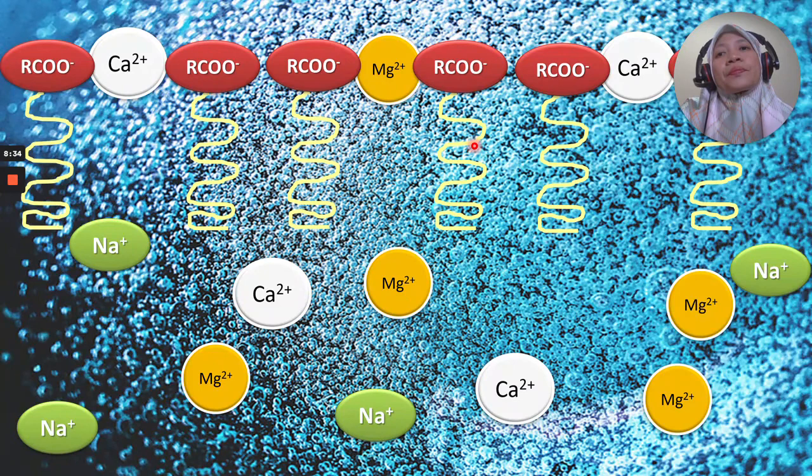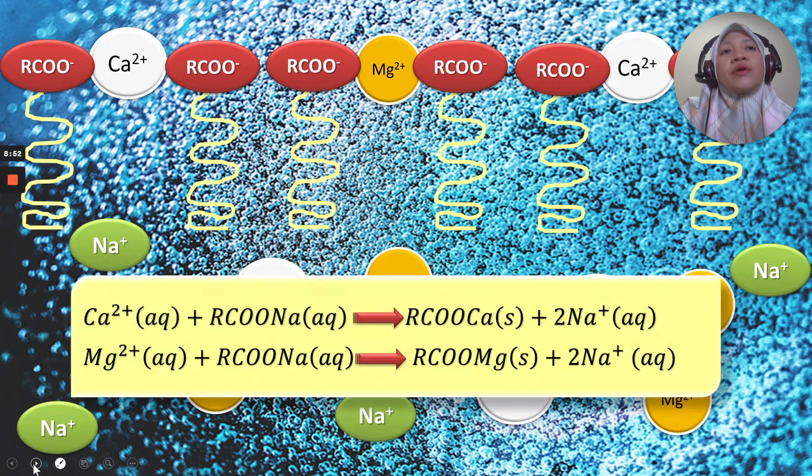Soap scum. Hence water hardness will affect alkaline cleaning, as the sodium soap will not emulsify the soil, but it reacts with the hardness present in the water. Hence fouling deposits and scale problems will increase. And this is the chemical reaction that is involved when soap is used in hot water.